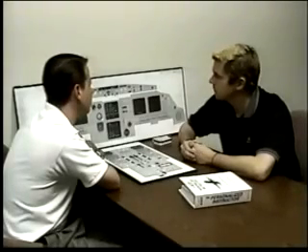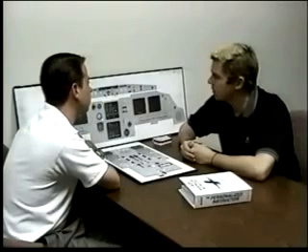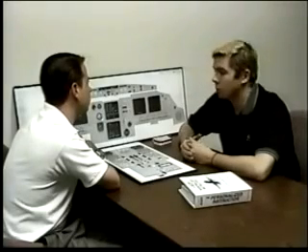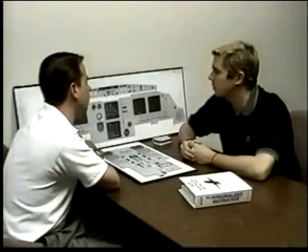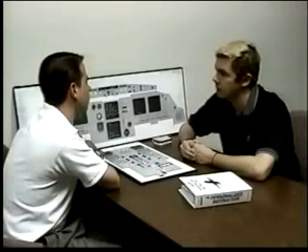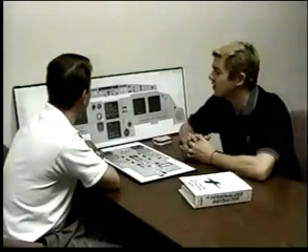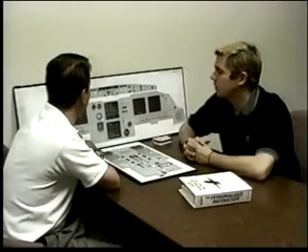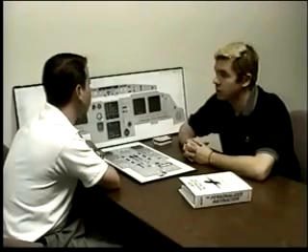Is there any caution to that? There is a slight caution. The policy at United right now is when we're cleared for the approach, we can arm the approach button, but we have to ensure that we won't capture the glide slope and start down until we've captured the localizer. So the caution really would be to ensure that you do not descend until engaging the localizer.